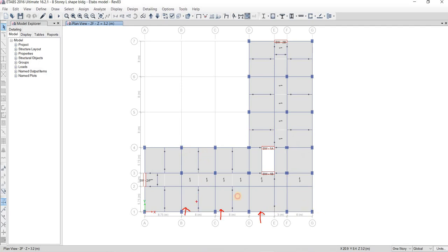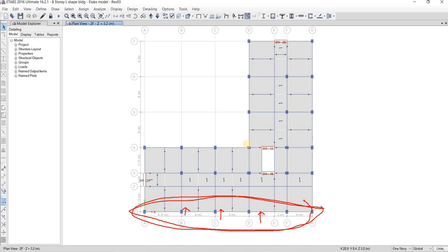You have to be careful, because if you increase the stiffness here alone, your building will somehow rotate. Okay, so you will have to study how to increase this one, or you can increase the size of this one. For example, this is for initial.